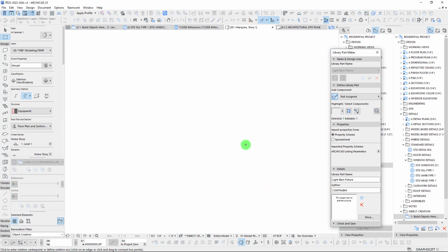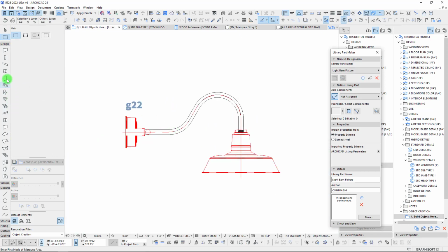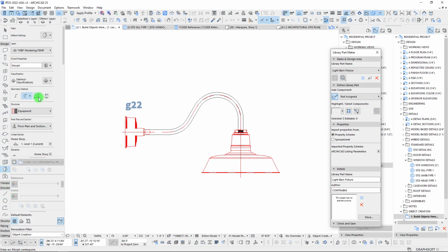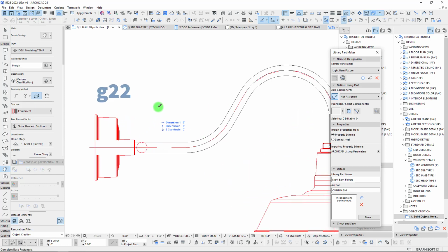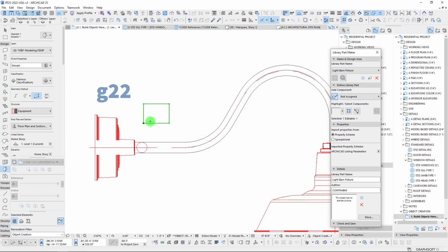Usually when rotating something like this, I like having a square element or a square face to work off of. So let's just create one right here. We'll just send this up a foot. We can put this right on our center line.